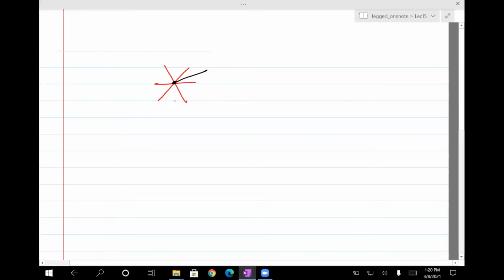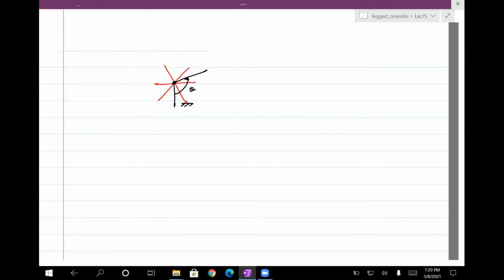And we need to find the angle made by the torso with the vertical. Okay, and so we've seen that you could use the transformation matrices, or you can use the spherical coordinates, but there's a simple way to do this with what is known as dummies in CoppeliaSim.